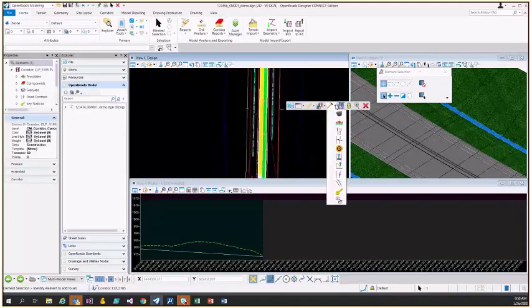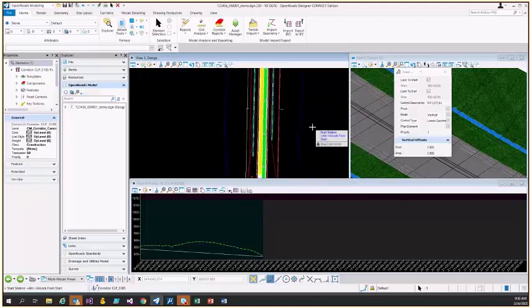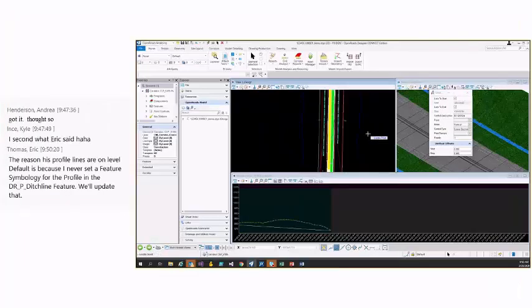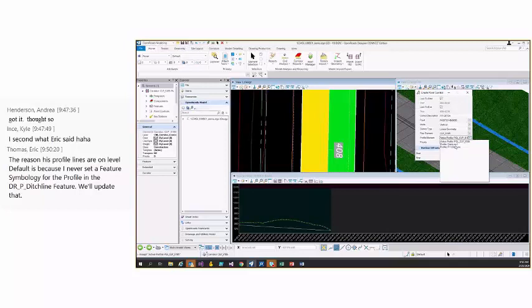Corridor. We're going to create a point control. I'm just going to have mine go the whole distance on a right ditch. The point is going to be right ditch inside, vertical, linear geometry. Now if you choose that, I should now see I have my other templates.